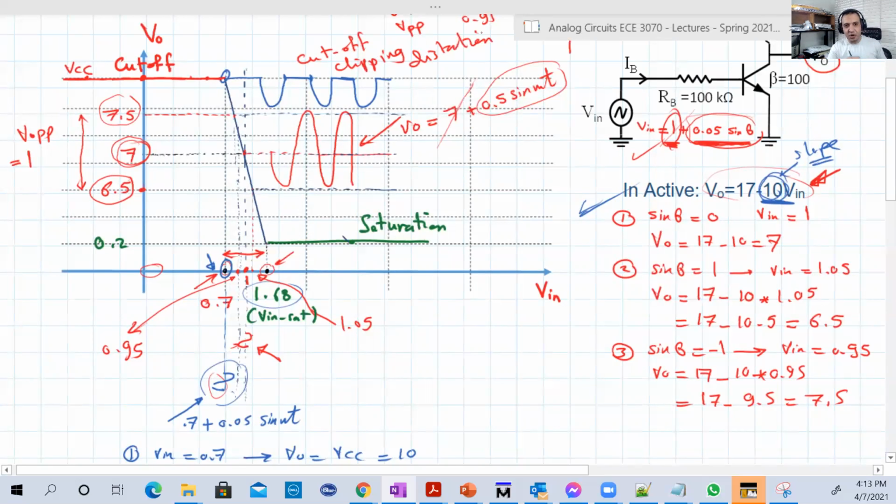Look, we have clipping everywhere in diodes, in transistors. And this is, of course, distortion for the input signal. The input signal was a sine wave like this, and look what we get, half of a sine wave. Yes, it's amplified, but where is the other half? Good. So it's not good to make the operating point near the cutoff region. Is it good to make it near the saturation region?